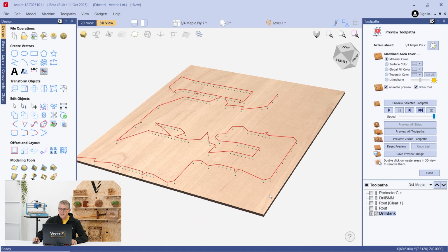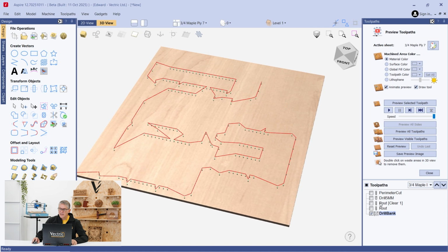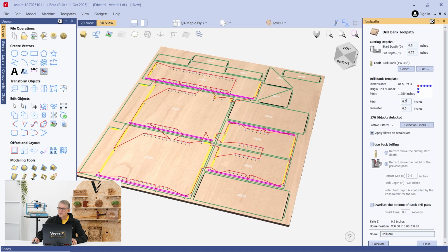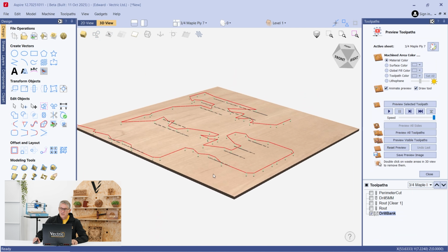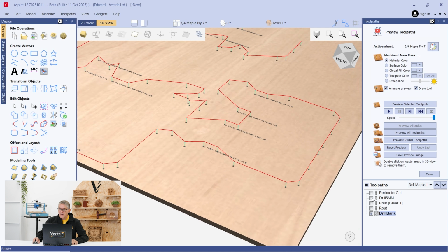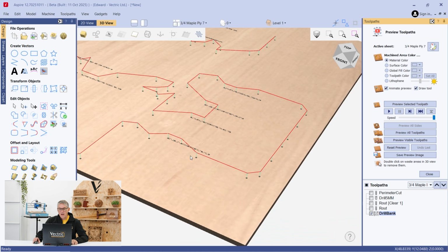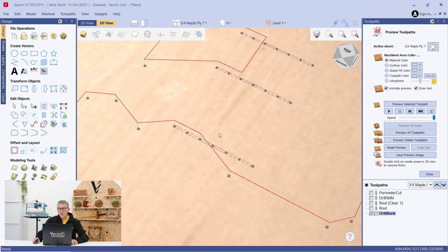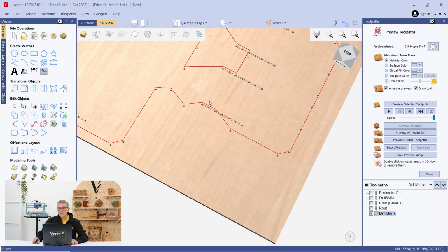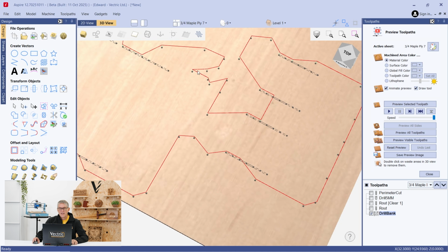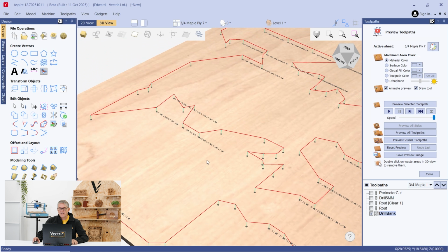And now what we should see is, he said confidently, that did not work. Let's just do that again. I've managed to reset my tolerances. Here we go. So now you can see we've gone from plunges for every hole in the conventional drill pattern to a pattern here where we're just seeing very few plunges, and you can see now little markers around the holes. That's showing you how we've automatically detected the efficient way of using your drill bank pattern to hit these holes.